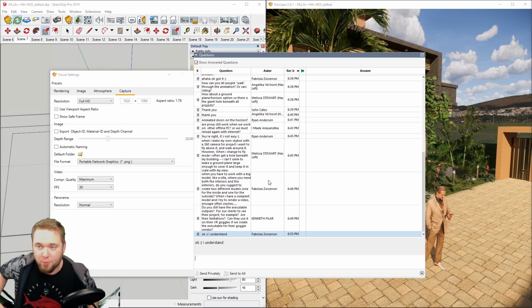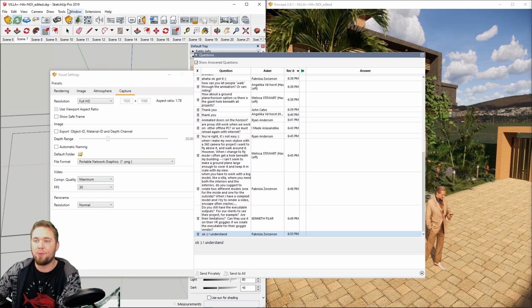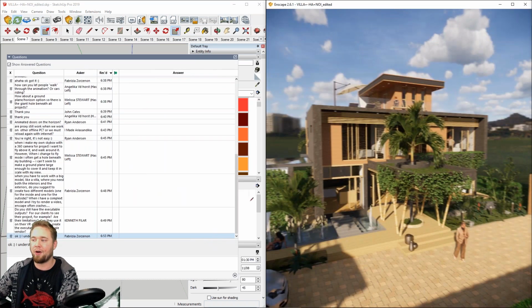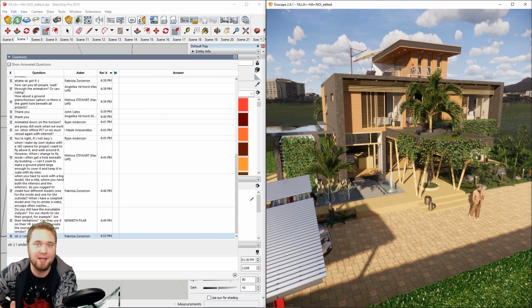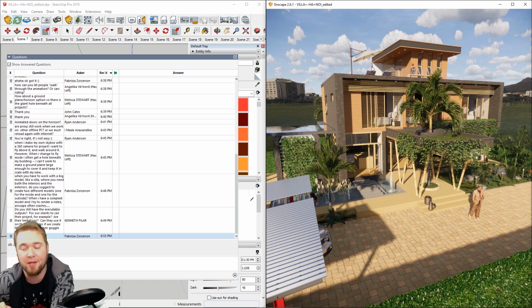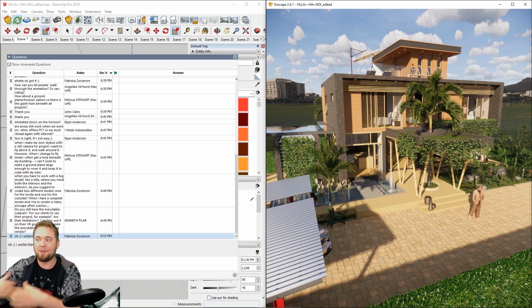Yes, Ken, we still have exe exports. We actually have added a web export. So for everybody who's not aware of that, you can export an exe file of the entirety of your Enscape project. You can brand that. You can choose your own loading screen. You can put in an interface overlay. You can name it differently. You can choose your own icon, so you can make it look like it's entirely yours. Enscape is just the translator.